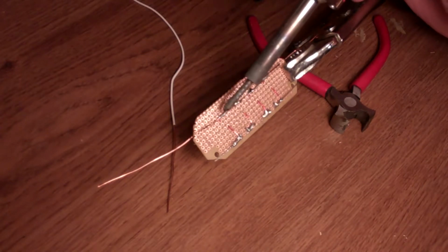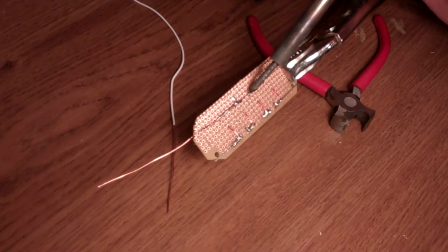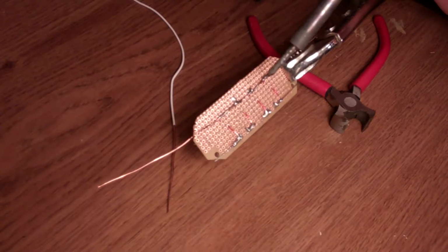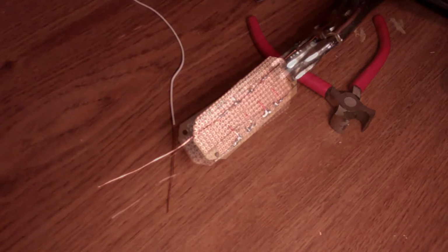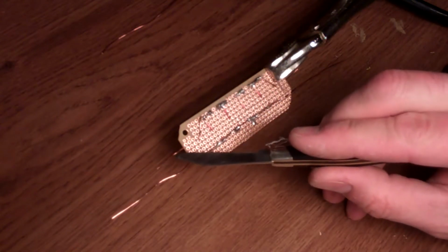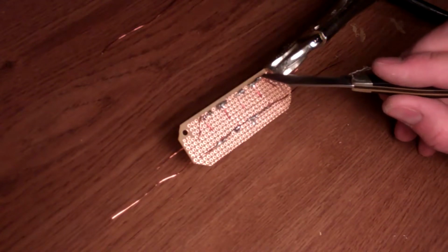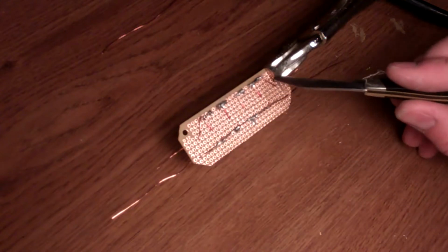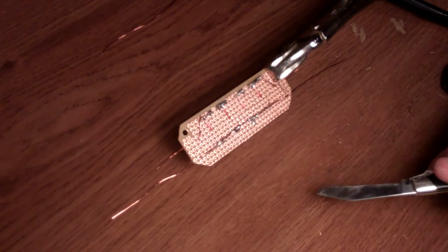And before soldering the magnet wire to anything, basically, as I said before, you want to make sure you got all of the coating scraped off the wire, or you're no way you're going to get any bead of solder onto it. So I've gone and added a couple more 22 gauge wires here and here, which will connect to the positive center conductor for the F-type coax connector here and here.